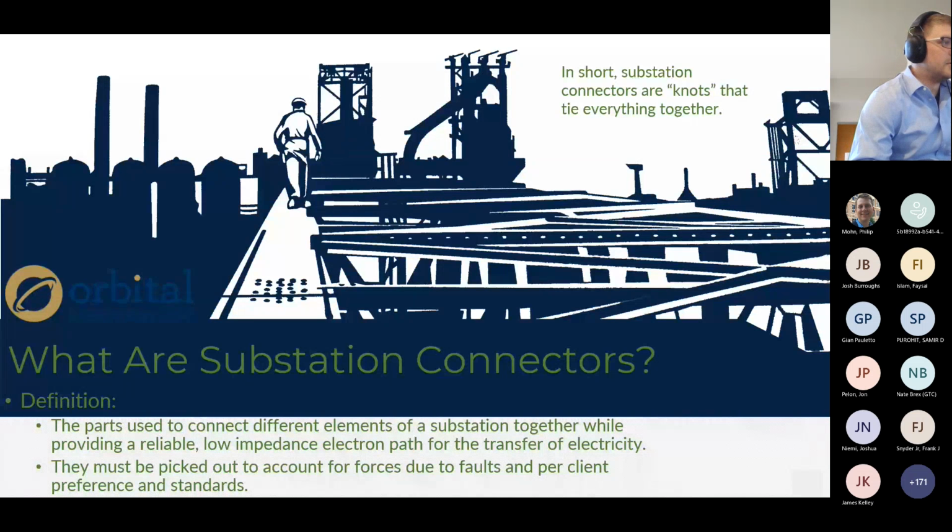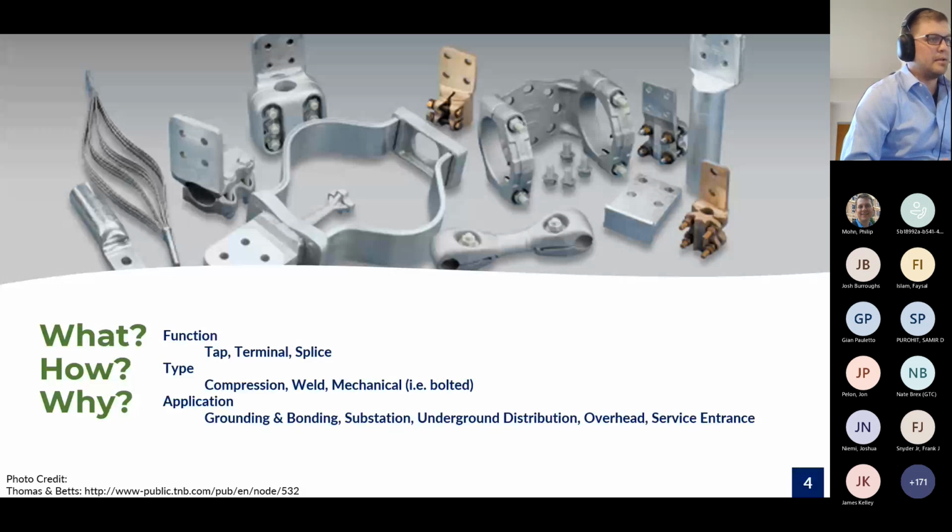Now, when you go into thinking about what type of connectors and all the different situations you would come across in a substation, I like to ask myself the three following questions: the what, the how, and the why. Now, what is the main function of this connector? Are we terminating onto a switch pad, a transformer pad, a breaker pad? Are we tapping off a main bus run to CCVTs or to station service? Are we expanding a bus? Maybe we have a breaker and a half scheme substation and we're putting in a whole new bay and we need to splice some new bus to an existing bus section.